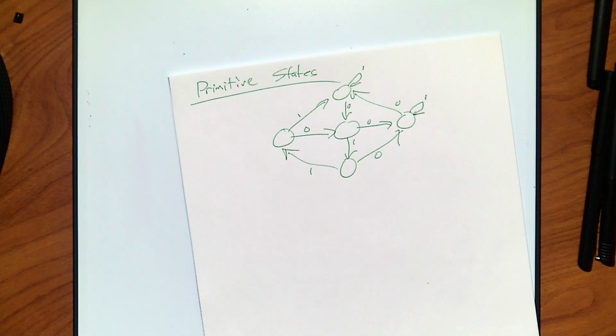Okay, here's the important thing about them. Right? These are just state graphs, and I have to put them somewhere. If I put them inside the states, a Moore machine, the output is only dependent upon what state you're in. Overall states means it's stored in memory. Memory is stable. So Moore machines have very stable outputs. If it's on the arrows, it's called a Mealy machine.